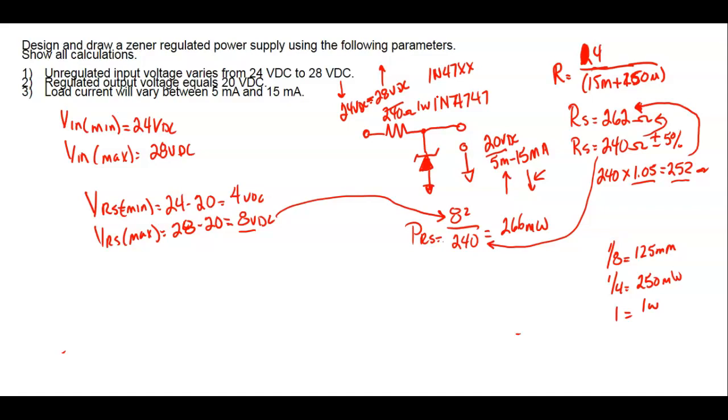Its physical size. So that's something y'all need to get used to looking at too. I'll try to find some for you so you can get a physical look at the different sizes these resistors would be depending on their wattage rating. Now, when you get into the big high wattage resistors, it's literally written on the side. But these little small ones, they're not written on the side, right? So you have to know by the physical size.